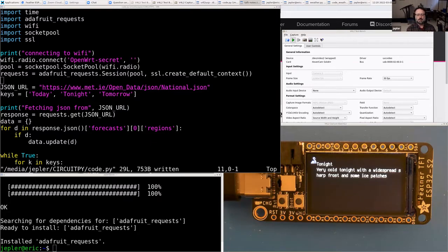But learning to write this common subset is not super difficult, and it brings huge advantages. You can work on tough logic bugs on your computer alone, not even involving the microcontroller, and then load it on the device and it'll work. You can use Python features like unit tests when you're running on your desktop computer. Then you put the resulting code back on your CircuitPython board and work out the part that turns the LED on.